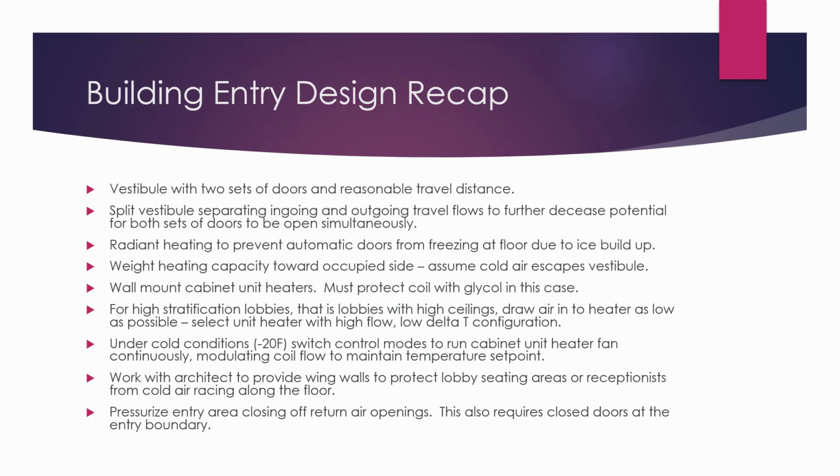Radiant heating to prevent automatic doors from freezing at the floor due to ice buildup. So if it's new construction, radiant floor is a good idea in an entry that has an automatic door. It's the best way to make sure that the track of that automatic door stays warm enough that there's no freezing.